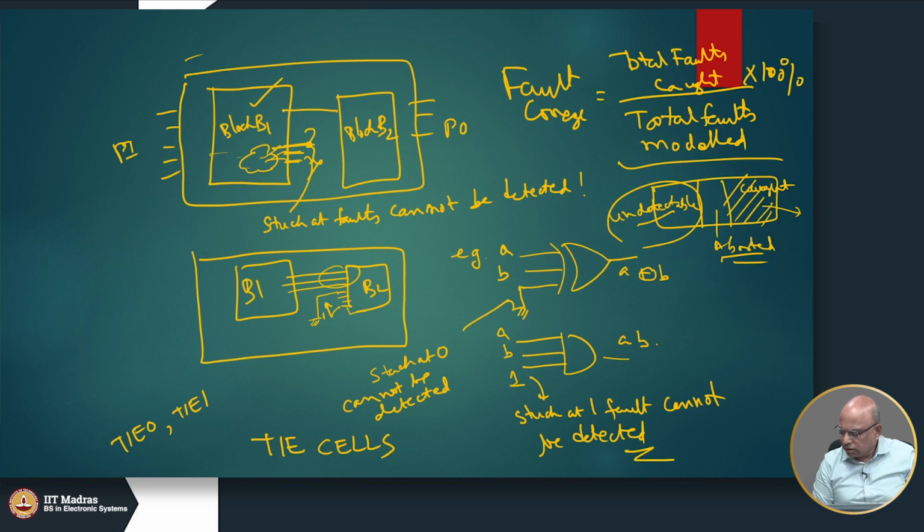but there may be something that we can do about aborted faults. Okay. So, if you join the industry in the test role, right, and you are asked to generate test vectors, the expectation is that you may have to reach some high number like 95%, 96%, 98%, etc. So, this is a target. Okay. We do understand that some small percentage of faults cannot be detected. So, you should be able to explain why you are not able to get 100%. And if people are convinced that indeed that is not possible to get 100%, they will accept your answer.